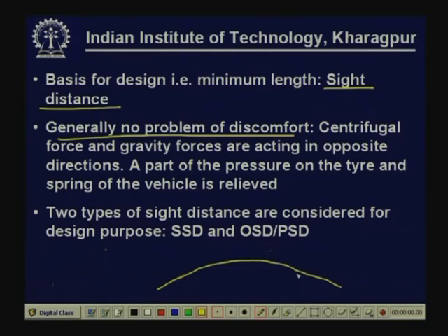When the vehicle is negotiating this curve, the centrifugal force is acting in the upward direction, and the gravity force is acting in the downward direction. Therefore, a part of the pressure on the tire and spring of the vehicle is actually relieved. So, there is as such no problem of discomfort to passengers. Therefore, the only consideration for the design of a summit curve is sight distance. That is what is important.